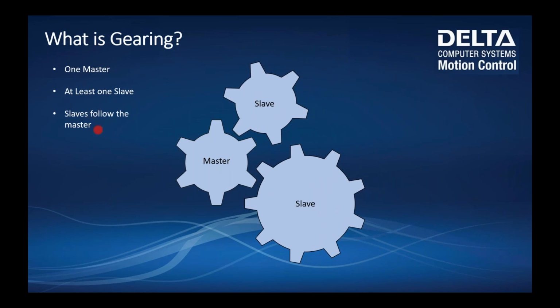So now, once we gear these together, these slaves are going to be following the master. So whenever this master moves, these slaves are going to be following, right? Just like what you'd expect from this physical setup here. So the axes or gears, they always stay synchronized. They're going to have targets that are going to make sure that these are always synchronized with each other. You can set up certain parameters and halts to make sure that, say, one of the axes goes a little bit too far off its target, each of these axes stops and one doesn't continue to move while the other is stopped.